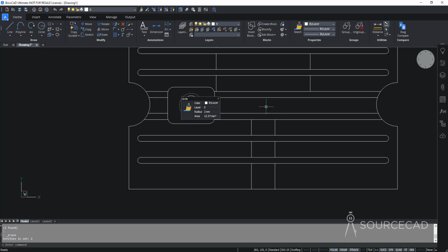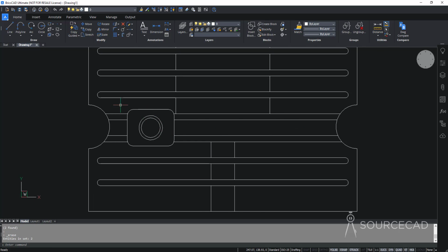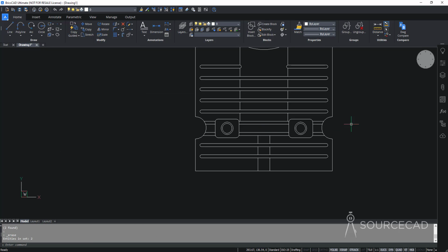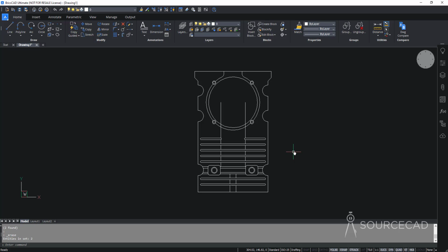Okay, that's done. Now we need to make a mirror image of this. So I'll select it all entirely, only these geometries, and I'll select mirror tool, and using, well, the points here and these midpoints are no longer available here because we just trimmed it. So I'll use another midpoint, which is here. So this midpoint to this midpoint, and press enter. There we are. We've got the exact mirror copy. Once again, a little bit of cleanup is required. So here it is, and here it is, and we can delete it. There. So we have added this detail as well.